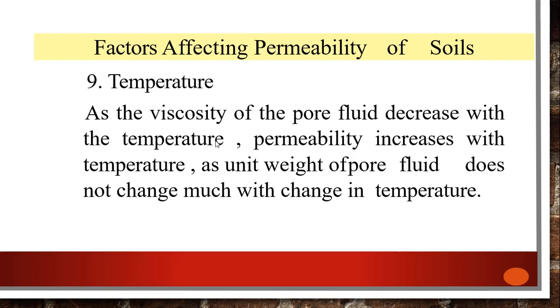Next factor is temperature. As the viscosity of the pore fluid decreases with the temperature, the permeability increases with the temperature. As the unit weight of a pore fluid does not change much with the change in temperature, as the temperature increases, the viscosity of a fluid will decrease. If the viscosity of a fluid decreases, it means the fluid can flow easily from the higher energy region to the lower energy region. In that case, we can say that the permeability of a soil will increase.